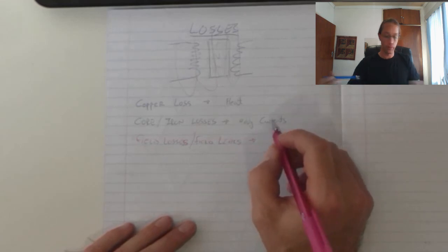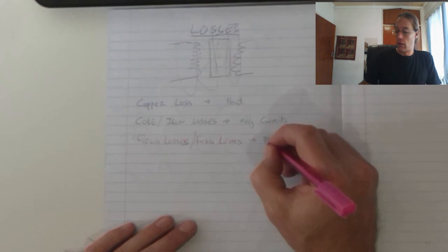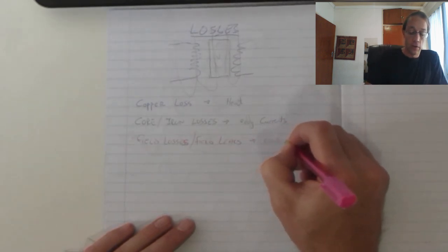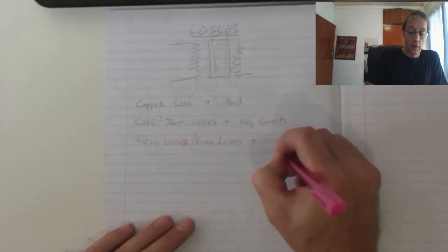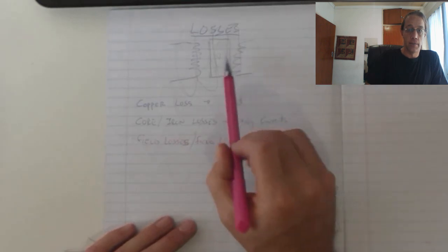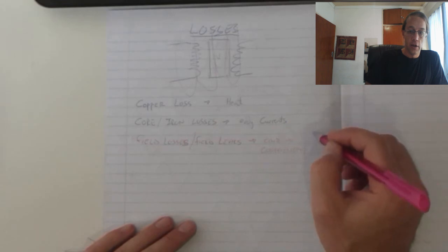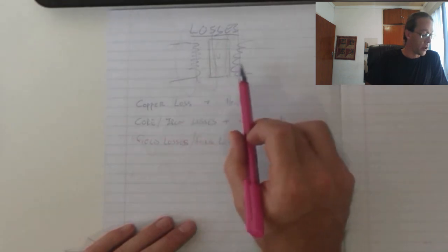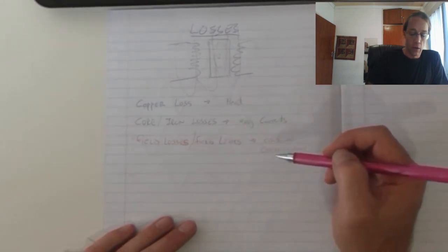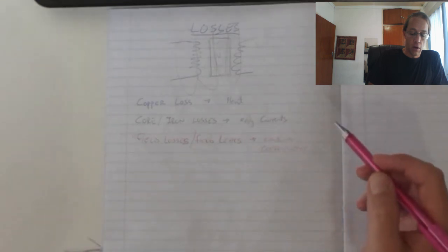But now if there's excessive current, then the core isn't going to conduct all the magnetic field. So as a result, my coupling coefficient, in other words, the amount of magnetic flux that influences both coils, will decrease. And because there's less flux cutting through both coils, we will have less voltage induced, and that will in turn decrease the amount of voltage that is induced.